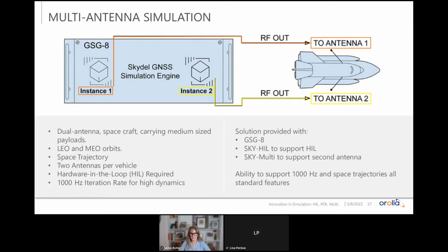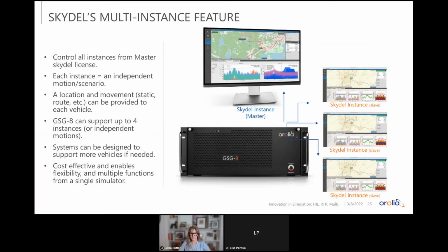If you're doing something like I explained with the 16 different radios or 16 different devices, then you still need to synchronize everything because you want everything to show the same time of day and the same area, but it's not as necessary to have it very, very accurately synced. It's not nanosecond-level sync that's needed, because they are actually independent receivers processing the signal. So it depends on the application, whether it's a single receiver with multiple antenna inputs or multiple receivers with multiple antennas. That will affect how accurate the time sync has to be.